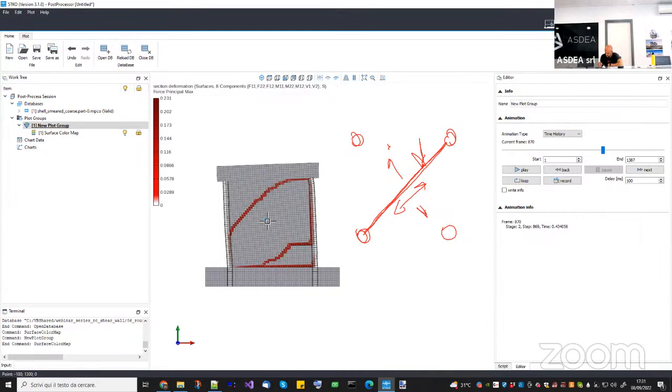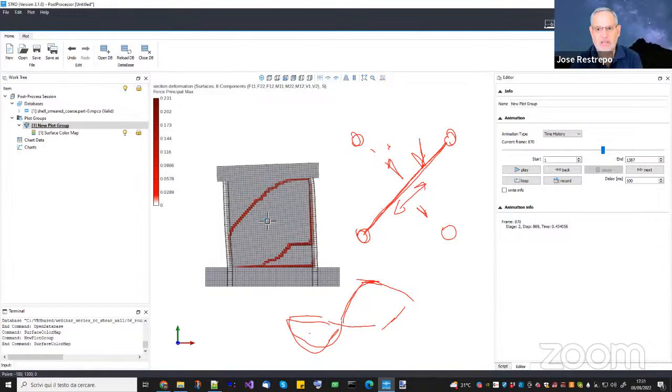In each one of them you assign a uniaxial material with only compression, no tension. But there are 2 of them, so it's basically like a shear response here. And then how strong they are depends on the transverse deformation. So they do have a coupling. Yes, absolutely.